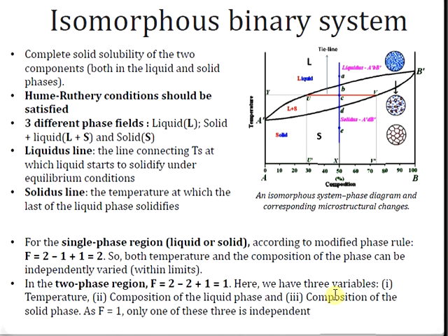So we can either choose temperature so that the composition of liquid phase, for example here in this line you see the line connecting this U and this is V. So here we fix the temperature value, so that the compositions coincide at the point U here and V at this point, U on liquidus line and V on solidus line.